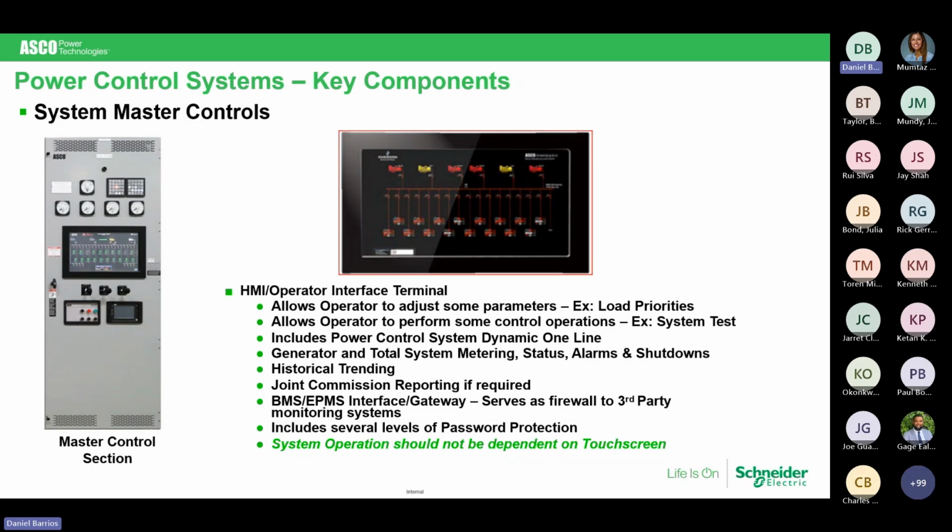It allows the operator to perform a system test. System tests can either be online or offline. Well, tell me why I'd want to do either. I've done some maintenance to my generators. I've maybe changed out some batteries or a starter or something. And all I want to simply do is test the system, get it to parallel between each of the generators, but I don't necessarily need to go online. I just want to do that.